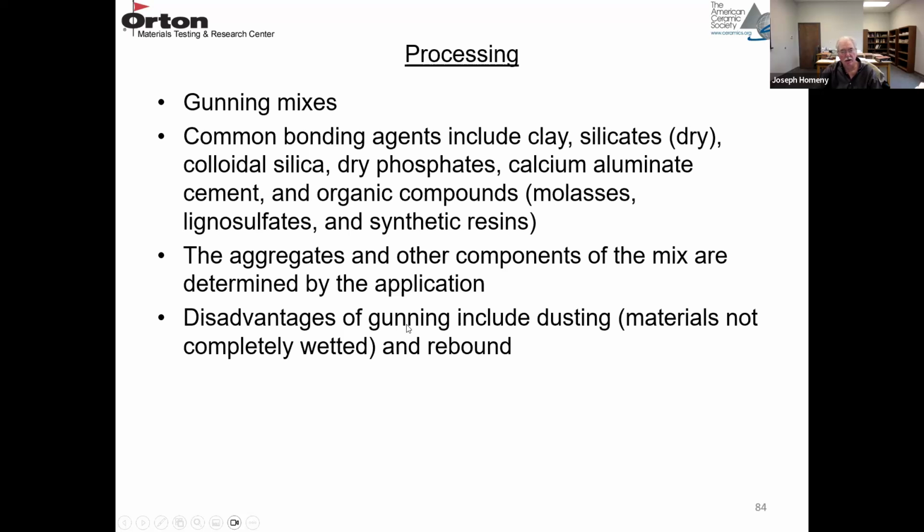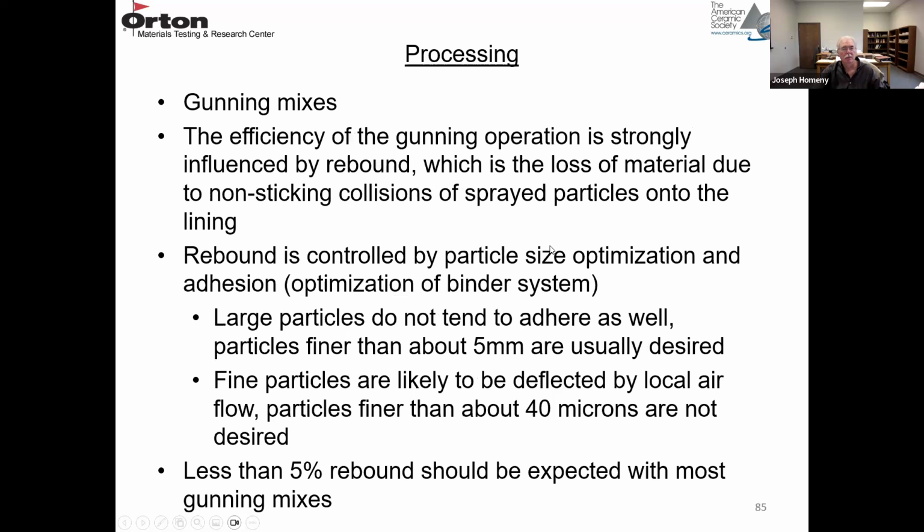The disadvantage of a gunning mix is something known as rebound. Materials that are not completely wetted may rebound off the surface, and then you have wasted material. How efficient a gunning operation is going to depend on the amount of rebound.